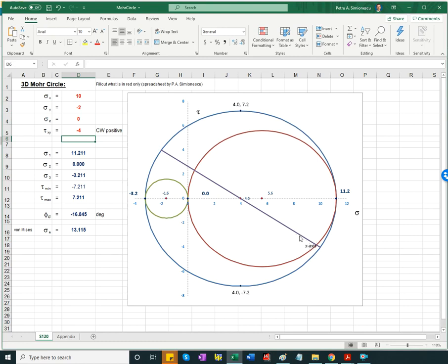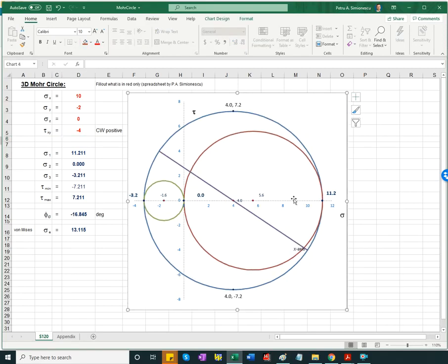Okay. So this time, to get from the stress element to the principal element, I need to rotate counterclockwise this much. So half of this angle, if I move it until these look very close to circles, I can measure this angle, although it's calculated, we have equations for it. Von Mises stress will be sigma 1, sigma 2 0, sigma 3 listed here.